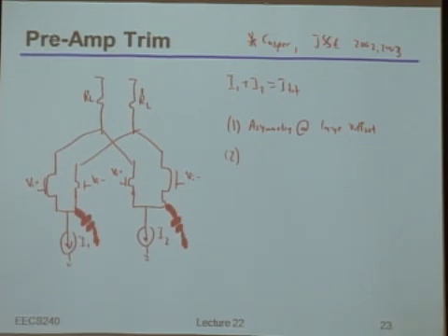By the way, your guys' life this year at least is even worse than previous years because you guys are dealing with 4PAM. Right? And I told you that your signal swings vary by 5x. So you have to cover not only this thing's own offset and the comparator offset, you also have to cover the range of variation in the signal itself in order to be able to set the thresholds in the right spot. Okay, so again, understanding how these things trade off with each other is pretty important because it could really drive which of these topologies you might happen to use to try and get the overall best trade-off between offset range and power and asymmetry and etc.